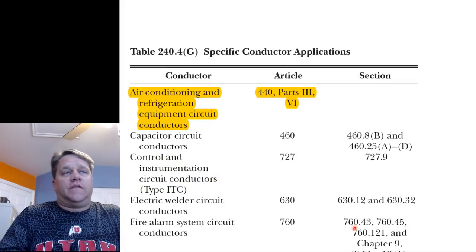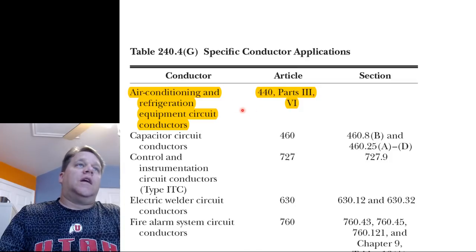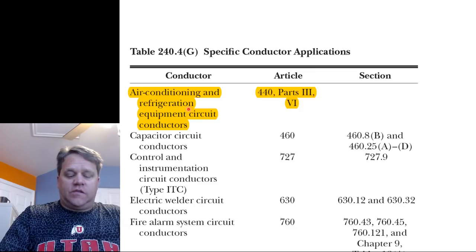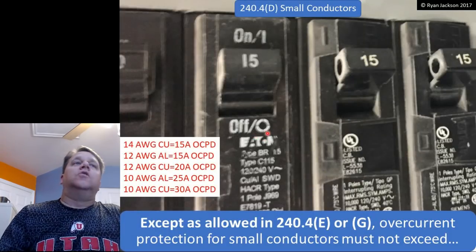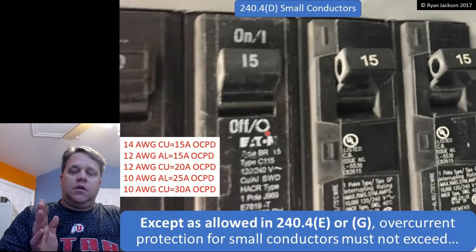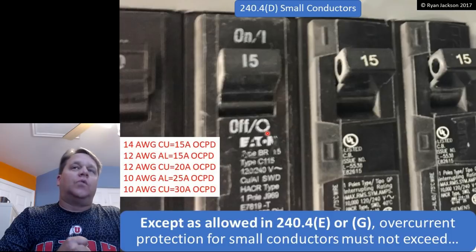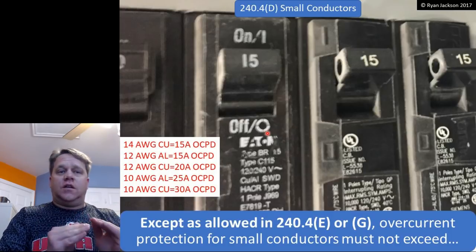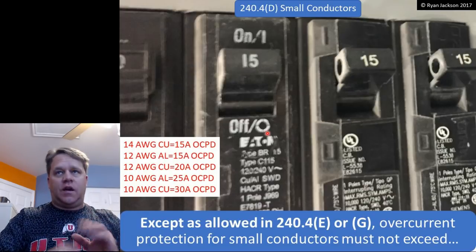G talks about specific applications, and it says you do not need to follow that rule for air conditioning. So let's reiterate this. This rule does not apply to air conditioners. You are not limited to a 15 amp breaker for 14 gauge copper. You're not limited to a 20 amp breaker for 12 gauge copper. You are not limited to 10 gauge copper for a 30 amp breaker. This rule does not apply for air conditioning circuits.